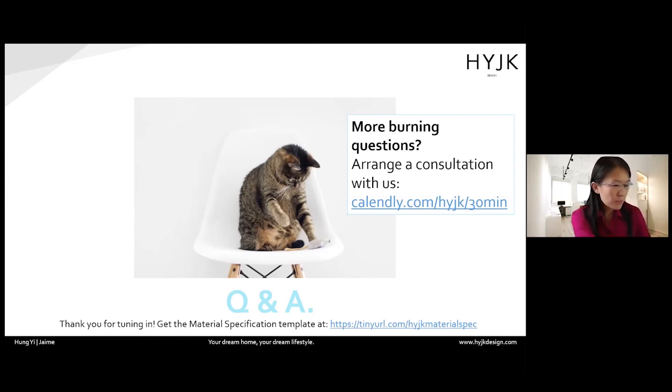Any treatment for dirty grout, or any ways to avoid stains? I would say cleaning regularly. If you leave the grout stains there for a very long time, it's going to be a lot more difficult to clean. They do have cleaners, like the one I'm using, Magic Clean. You can just squirt on it and leave it there for a while before cleaning, so the chemicals actually do most of the work for you.